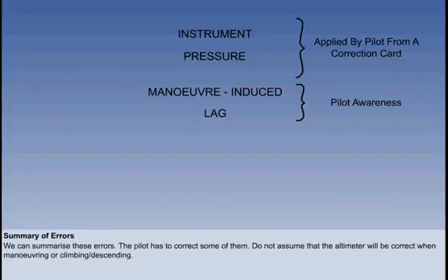If we correct or allow for just these 4 and set 1013 and don't apply temperature corrections, we would be flying correctly at flight levels or pressure altitude.